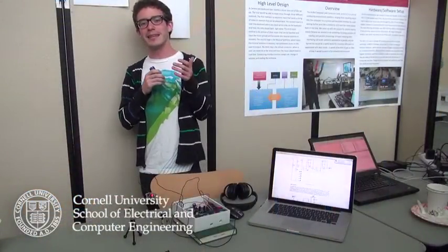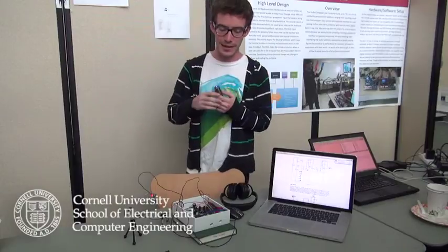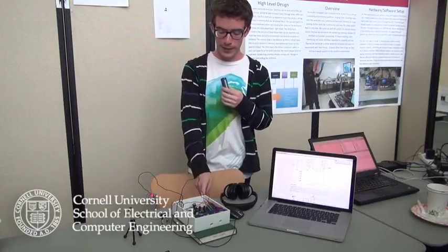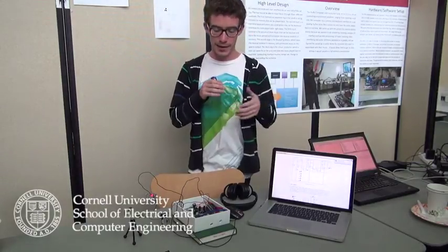So essentially we made a microphone using a laser, and the way that it works is you reflect it off a piece of glass. The piece of glass can be anything from a window to like the surface of a building, just any reflective surface, and it reflects back to this photo transistor over here, and it goes through amplification and filtering, and you can actually listen to it using headphones.